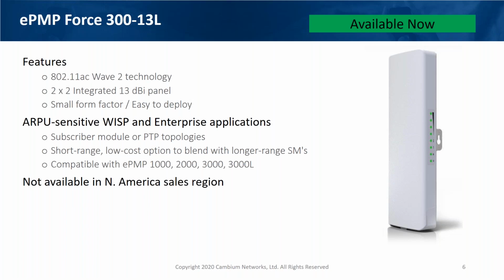It has that built-in spectrum analyzer, and it has a little bit higher performance processor, so it can go all the way up to that 600 megabits per second. The 13L is about 20% less in price, has a little bit wider channel, doesn't have the spectrum analyzer, but still gives that 400 or so megabits per second capacity.